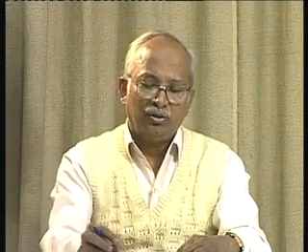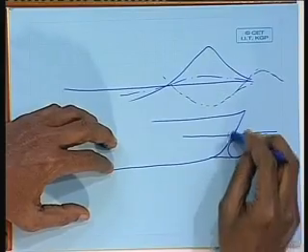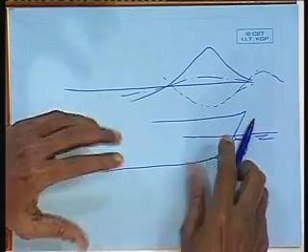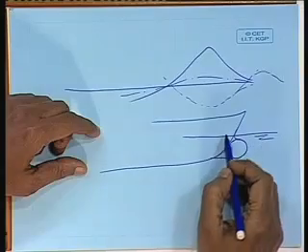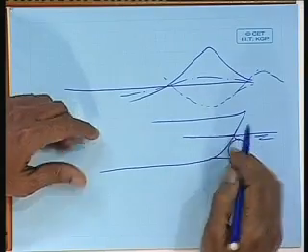What other effect does the bulb have? I am bringing down the volume below by putting a bulb here. The volume that was here, I have brought it down. Do you understand that? My underwater volume increases. Therefore, the volume distribution of the free surface, the area distribution of the free surface, reduces. So, now I am in a position to give a waterline which is finer.